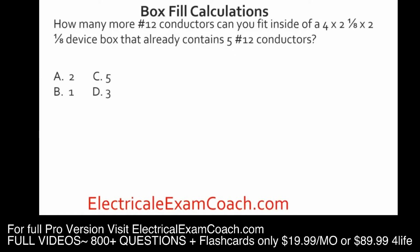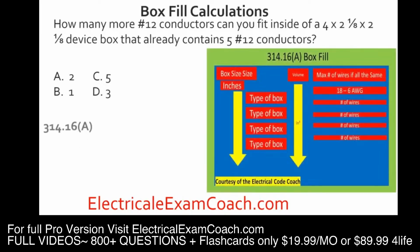How many more number 12 conductors can you fit inside of a 4 by 2 1/8 by 2 1/8 device box that already contains 5 number 12 conductors? For this one, we're going to head back to our table 314.16(A). First, let's find out how many wires it can hold originally. It can hold 6. We already have 5, so we take 6 minus 5 equals 1, and we can put one more conductor inside of this box.